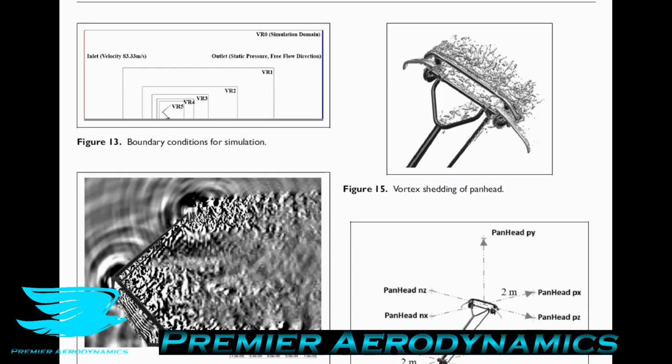So to sample this properly, the sampling law is you need to have at least twice the sampling frequency of this frequency, because if you don't, then you won't pick up the frequency properly. What will happen is you will start registering this frequency as not 100 hertz, and it will come up as a different hertz. And it'll be pretty much noise to some extent. So to measure this frequency accurately, you need to have at least 200 hertz.